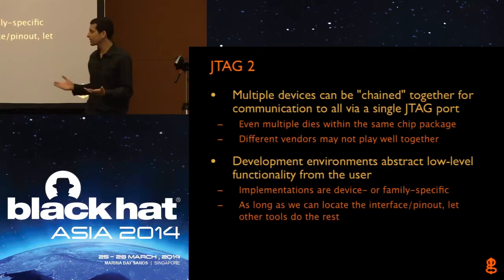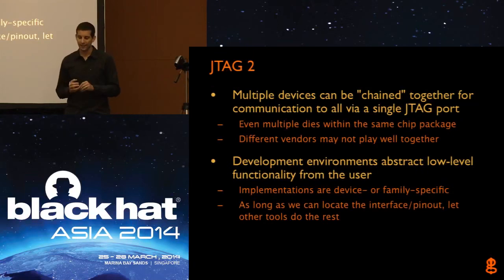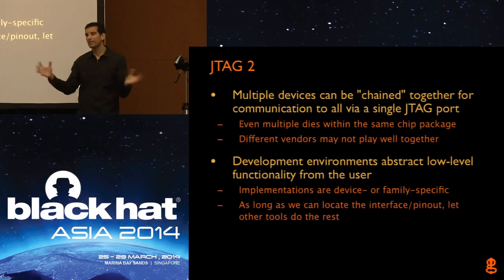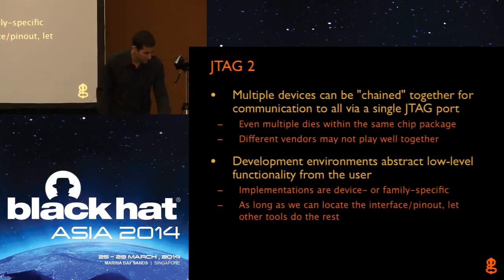Usually what I tell people is to try to put yourself in the mindset of the legitimate engineer that designed the product. So say we're looking at an access point with a Broadcom BCM4702. I would try to find out if there's a development environment for the 4702, and whether there's a recommended JTAG hardware to use for that architecture. I believe that was an ARM-based architecture, so I'd probably find something that supports ARM. Because then everything's abstracted, and we don't have to worry about low-level stuff anymore. So that makes it nice.